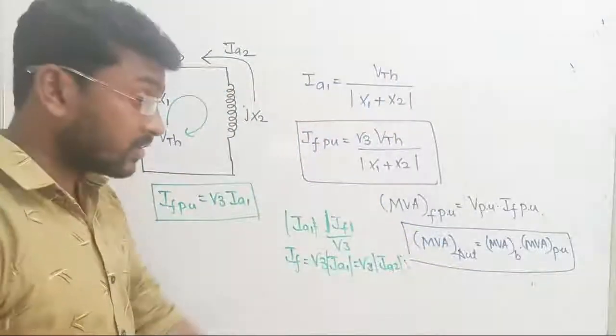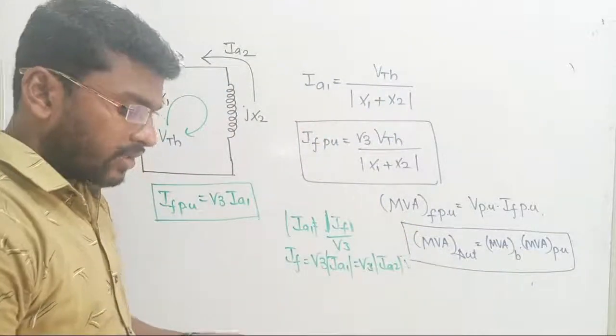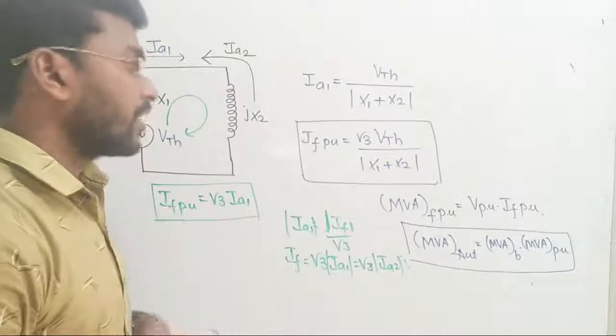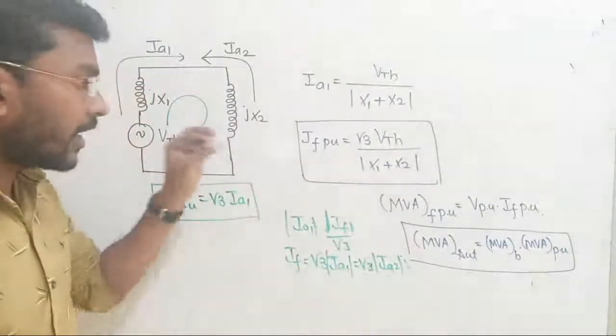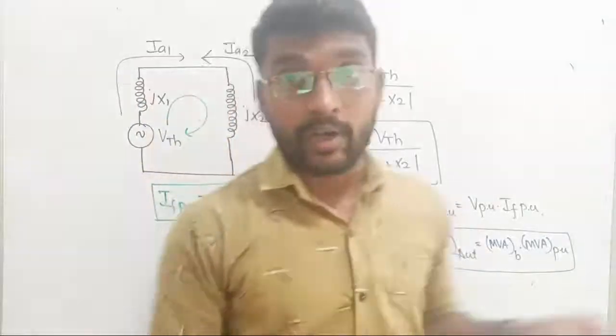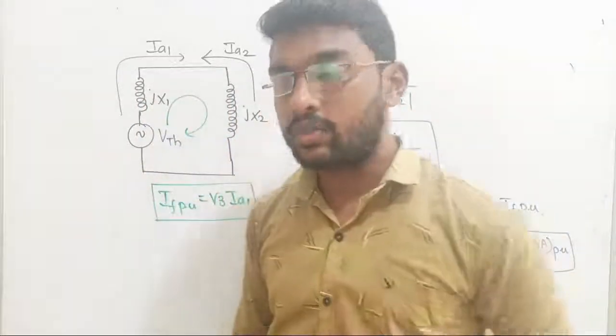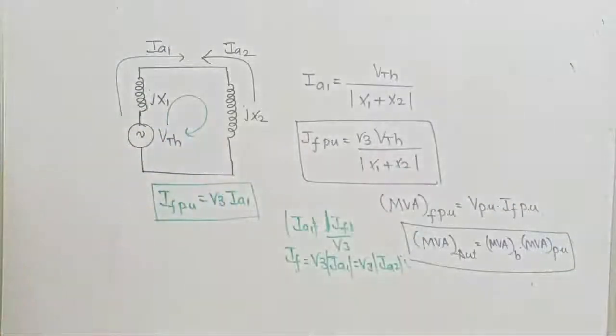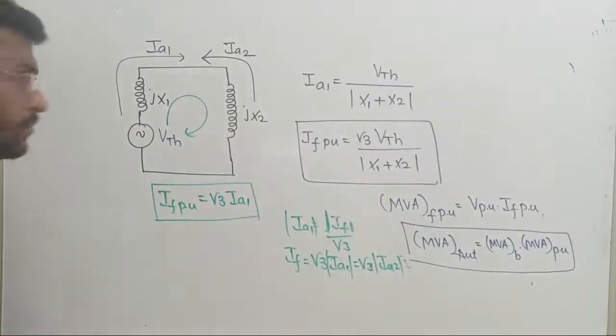Very important, because they can ask 2 more questions. Anyway, you understood how we are calculating the value of fault current. Line to ground fault, line to line fault, we know how it comes. One more possibility will be there, 2 lines might be directly shorted at the ground. That is the last possibility. Let us proceed with that one, right? So let me take the last case.